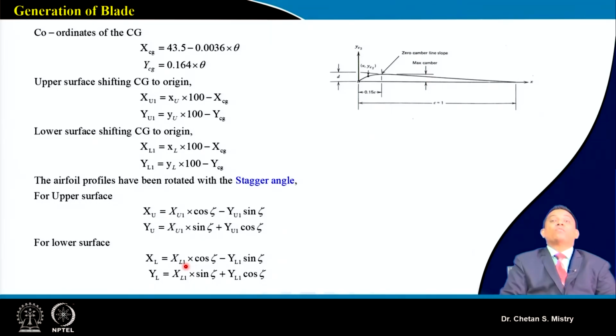And when we are looking for this curve to be smooth, we need to have more points. So just decide, say, more than 500 points for the upper surface, and the same way more than 500 points for the lower surface. That's what will give you continuous curvature without zigzag. Okay, so I'm sure you can do this programming for making this blade.